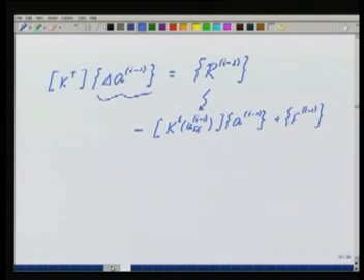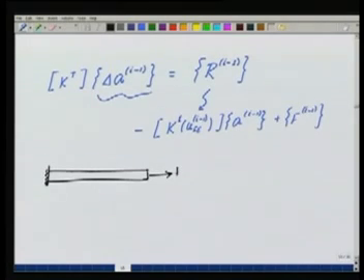What do you do with respect to the boundary conditions on ΔA? So if I have this bar, remember, with F here, okay, so here my U is given as 0, let's say, or it could be given as some other value, but wherever the U is specified, my ΔA has to be 0 at that point.